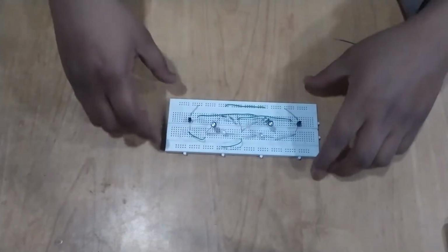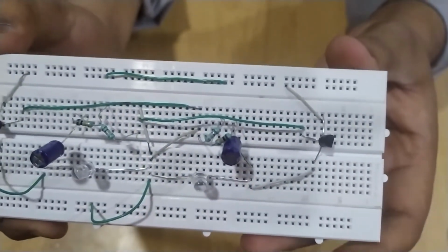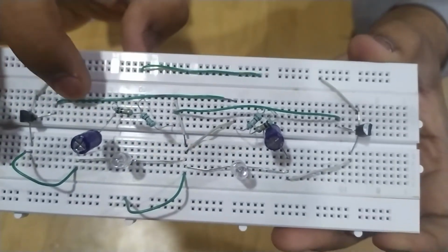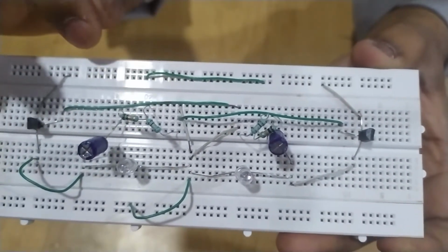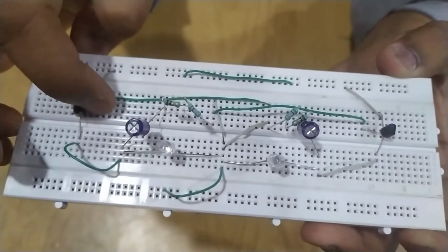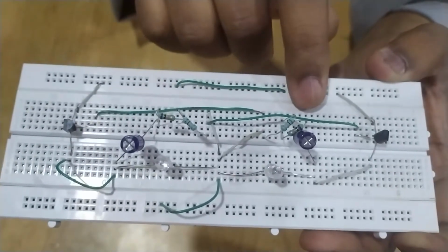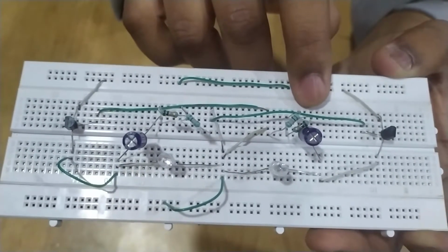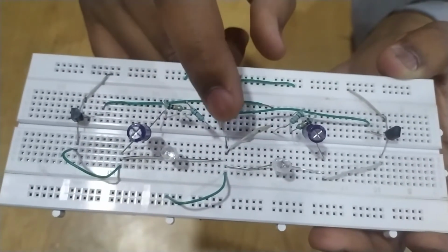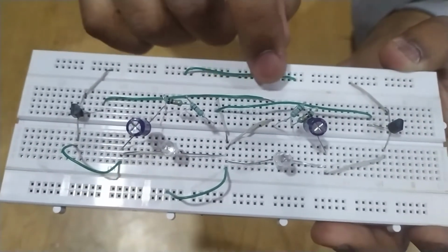Okay, so I made one mistake while connecting the components. So this wire and this wire, these connections are not correct. So this point from base is required to go to the junction where resistance and the capacitor is meeting. So I've connected it to the point where LED and the resistors are meeting. So this is wrong. So I'm going to connect these two connections.